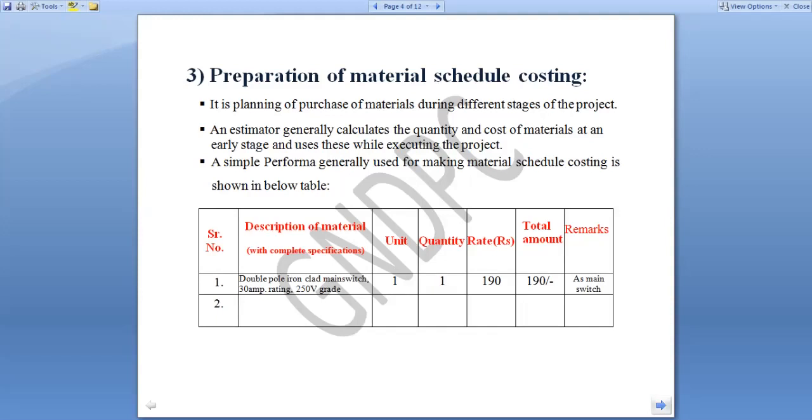We can explain the procedure with the help of an example, say, an electrification project for a building. Now, while determining the quantity of material for any building, it is essential to prepare a plan of the building, marking electrical points, switchboard, and main board, which actually constitute energy meter and main switchboard on the plan through approved electrical symbols.